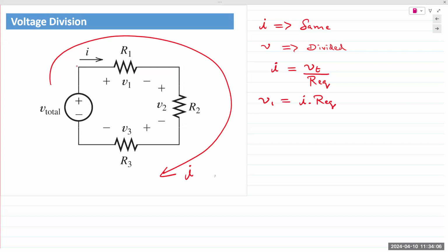So the total current I that is flowing in the circuit would be the combined effort of R1, R2, and R3. And so the combined effort of all three in the series circuit would be R1 plus R2 plus R3, Req. So when we apply Ohm's law, it gives me I is equal to V over R, but R in this case, as seen by the source, is R1 plus R2 plus R3, Req. So that was the question being asked. Why is it Req? And the answer is that's the total being seen from the perspective of the source.